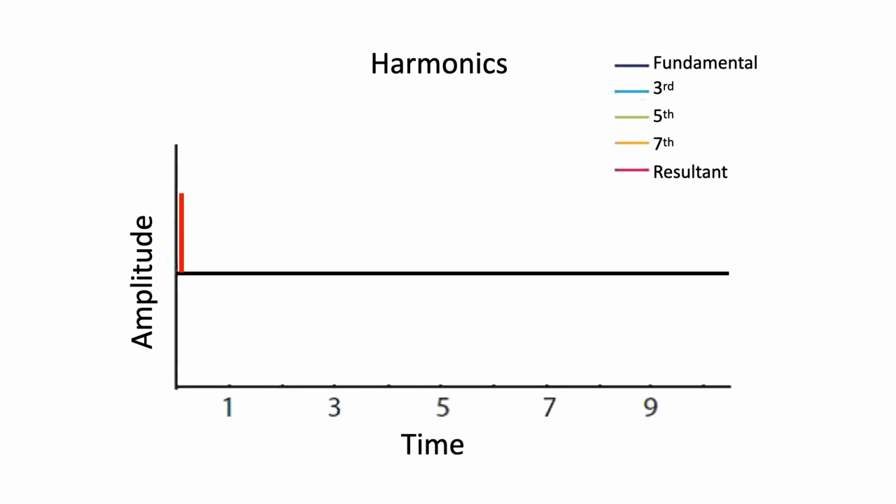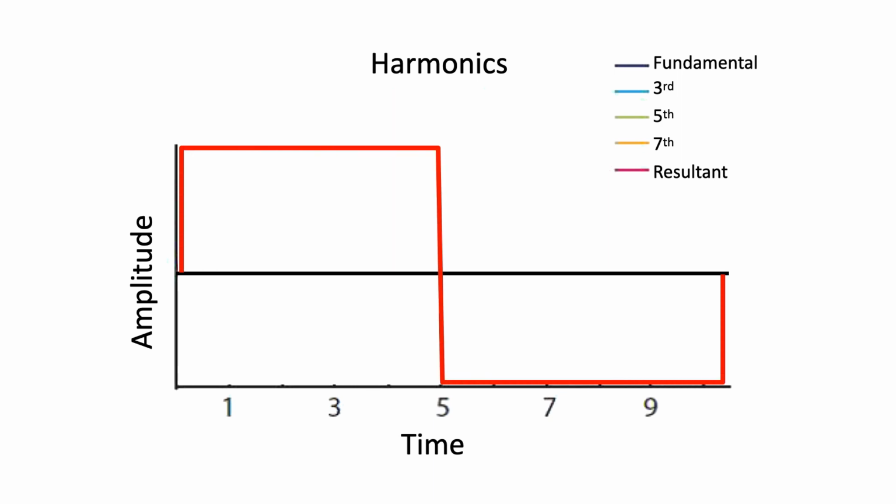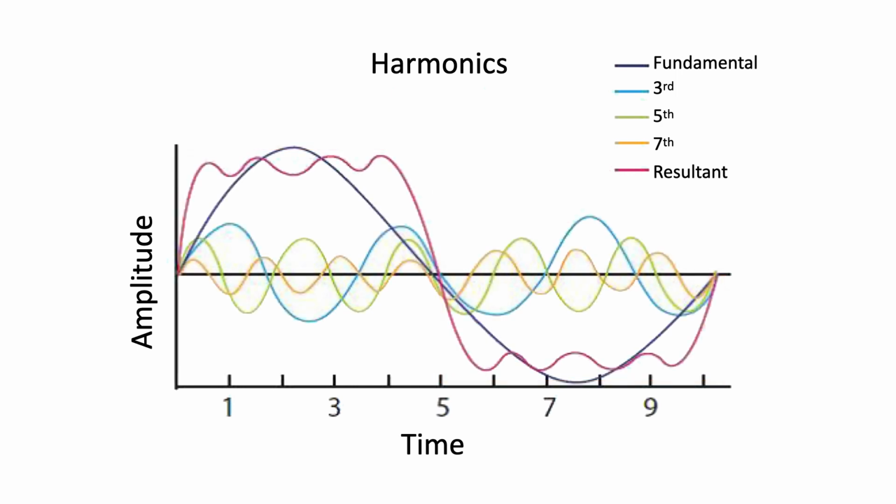When a non-linear load, such as a rectifier, is connected to the system, it draws a current that is not necessarily sinusoidal. The current waveform can become quite complex depending on the type of load and its interaction with other components in the system. All waveforms, no matter how complex, as long as they are repetitive, can be broken down into the sum of the fundamental sinusoidal wave plus multiples or harmonics of the fundamental frequency. And in order to analyze this, we have a system called Fourier analysis.